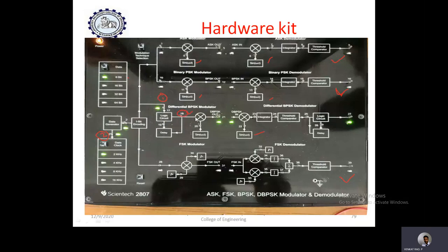That differential data is connected to the general PSK block. The general PSK block means just by multiplying the carrier signal, it will generate a two-phase-shifted waveform of the modulated signal. That is considered as DPSK. And the demodulation can be observed directly at this particular point. Now, of course, here a coherent carrier is used, but generally DPSK is used for detecting the signals in a non-coherent way.